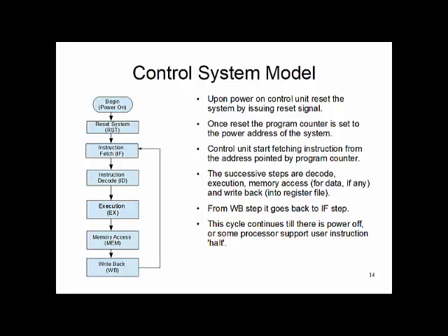Then it repeats from the instruction fetch: fetch the next instruction, decode and register fetch, execute and crunch the numbers, then memory access if needed, and then write back, and then go back to the fetch, and this goes on forever from the turn on, okay, till you turn off. So everything goes off right there.